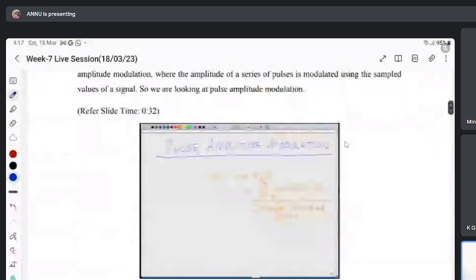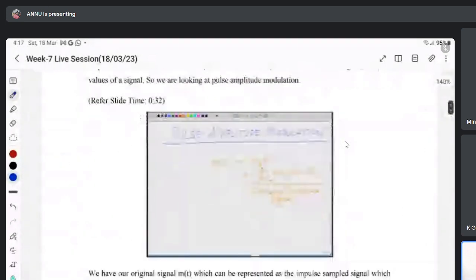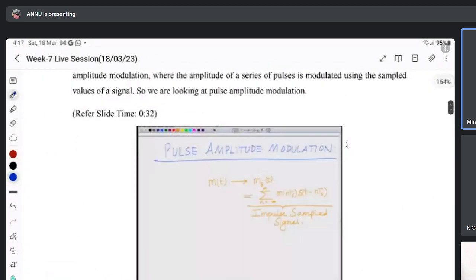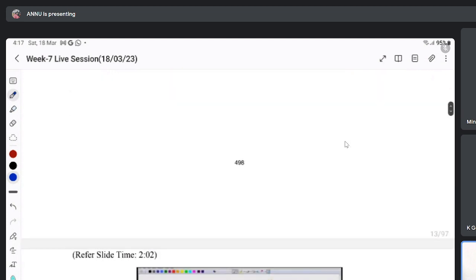Why is equalization needed? Ma'am, because there is distortion of this message spectrum because of this sinc function. So to correct for that, phase distortion and amplitude distortion as well. Phase distortion by 90 degrees and amplitude distortion by whatever the magnitude of this sinc is. Okay, nice, you have read then. Can you tell me this output?